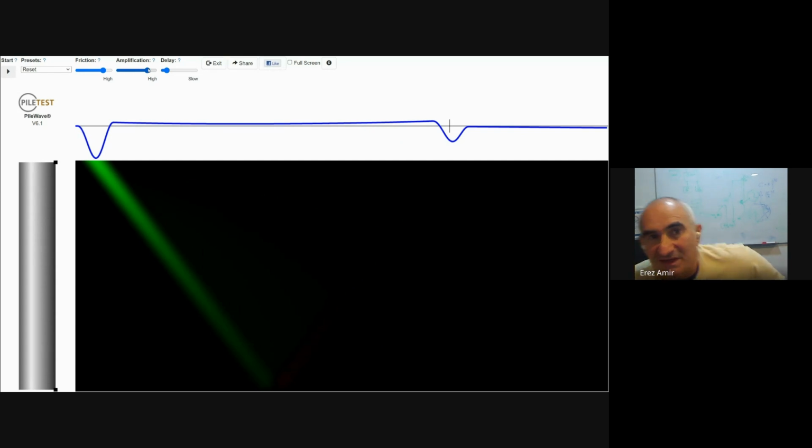Okay, now everything that I say here is a bit simplified because, as you know, soil profile is not always uniform, and sometimes the friction at different layers is different. You have a soft layer, and then at the bottom you have a harder layer, or even rock. Everything changes it, but still, as a principle, that's a rule that you need to understand: amplification compensates friction.